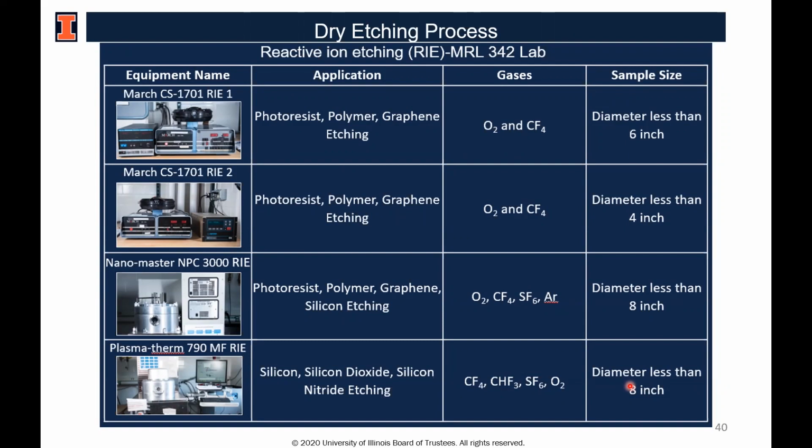So when we are talking about dry etching, we can actually purposely choose which type of etching, either chemical or physical, is more predominant in the dry etching process, so that we can control the etching profile to achieve the desired etching depth and the etching shape.